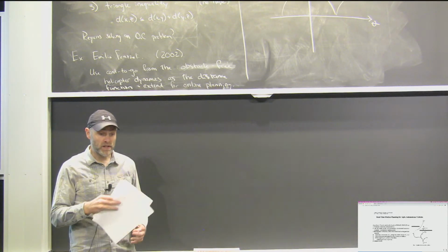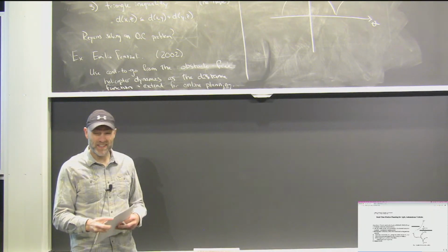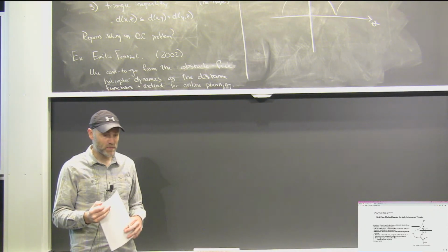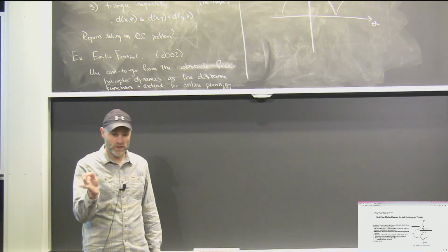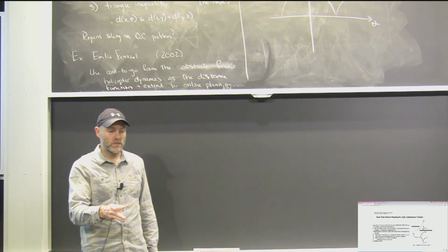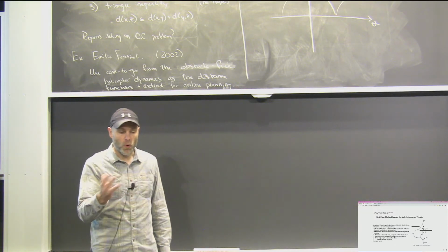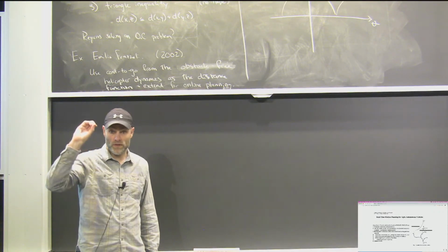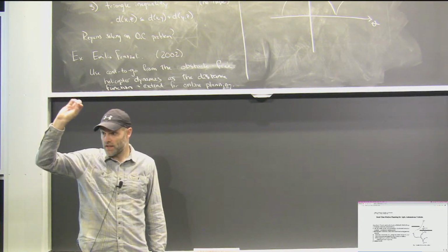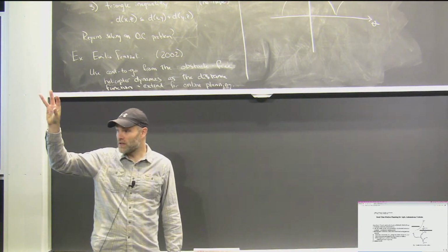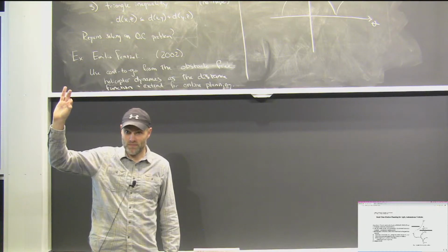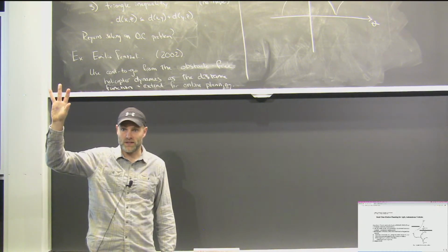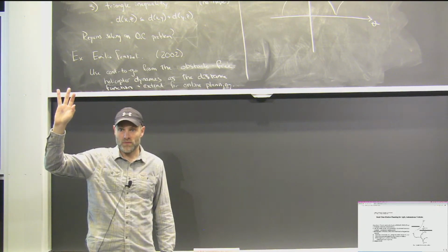There's a bunch of variants of this. That seemed a little bit helicopter or ground vehicle specific, and you had to find a way to exploit the symmetries and solve a value iteration problem. There are more generic versions of this. We had a version back in the day that would solve an LQR problem, for instance. You take the cost to go for the linearized system in order to come up with a distance metric for the nonlinear system.